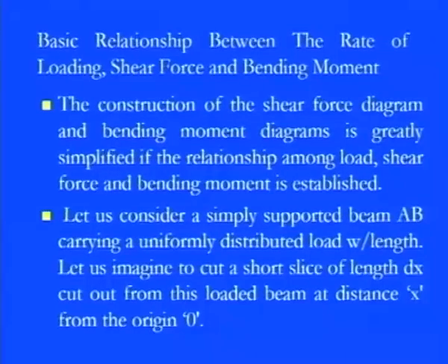So we would like to first set up the basic relationship between the rate of loading, shear force and bending moment, because whatever the rate of loading or kind of loads there are, the point load or the concentrated load, due to that the shear forces are generated in the cantilever beam or the simply supported beam, and due to that the bending moments arise. So our main intention is to find what the relations are between the shear force, bending moment and these kinds of loadings. For that, the construction of the shear force diagram and bending moment diagram becomes really simplified if the relationship among the load, shear force and bending moment is established.